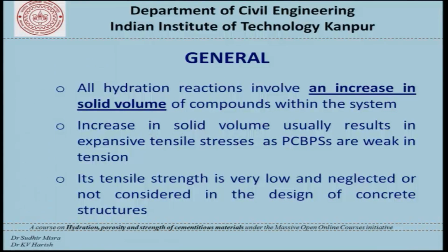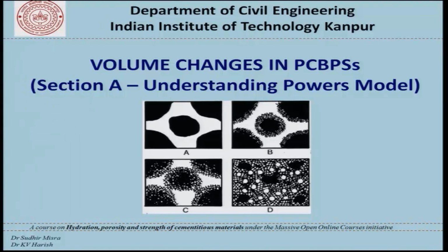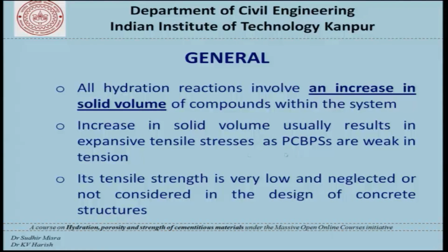The increase in solid volume usually results in expansive stresses, as Portland cement based systems are weak in tension. The meaning is that when these hydration compounds are formed with time, usually they try to occupy the available space, but many times for certain compounds you may not have enough space within the system. In those cases they may create some stresses, and those stresses are generally tensile in nature.